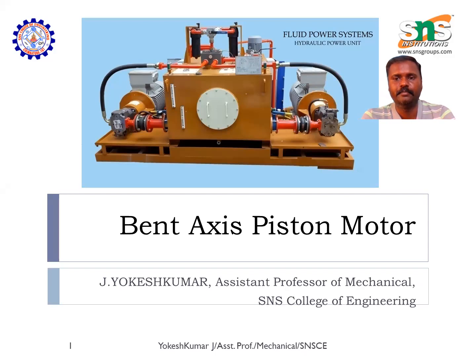Here, the input shaft and the rotating cylinder block are not in an inline manner. The axis of the rotating cylinder block and the drive shaft is slightly bent. The speed of rotation of the motor depends upon the axis bend in the motor. So let us discuss the constructional and operating features of the bent axis piston motor.